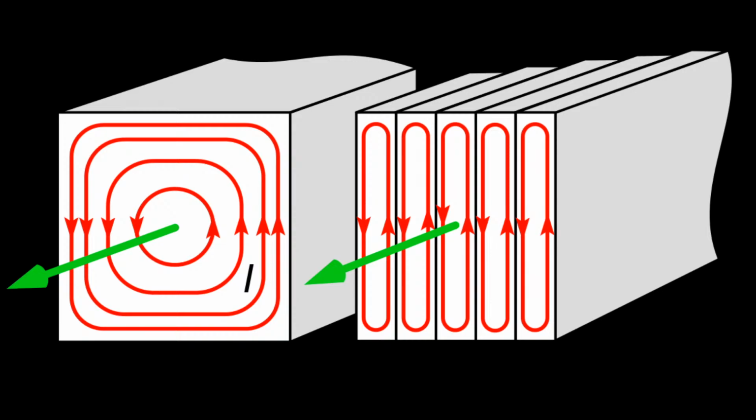So you find it the turning, just small part only. Turning small part means you reduce the current, reduce the energy, be less. So this one is how we go to solve the eddy current. So we're using the laminate iron core. Laminate, from here you can say about the painting. Paint the iron core at the behind one, or you're using the insulation material to create the behind layer. So this one is how to reduce the eddy current.